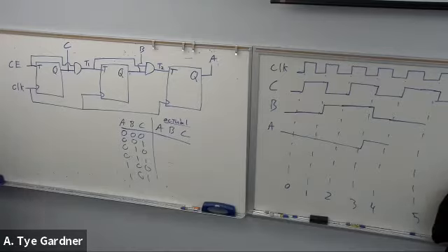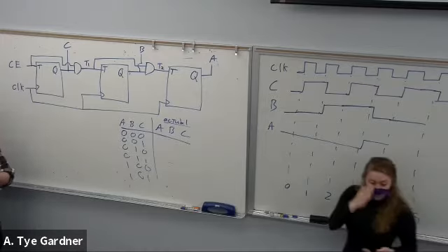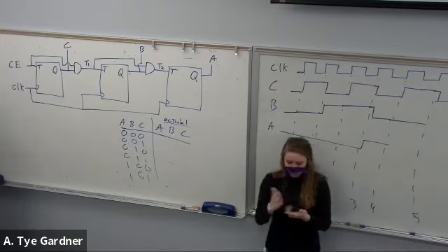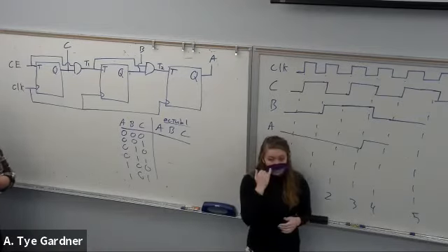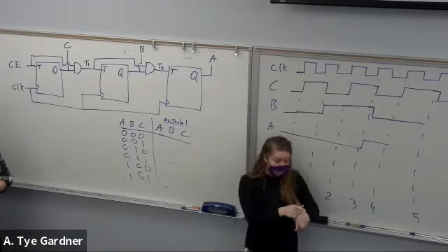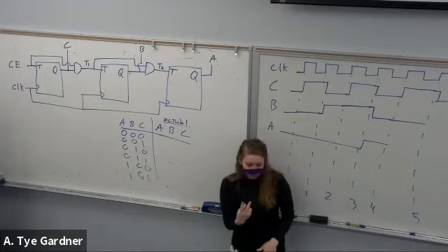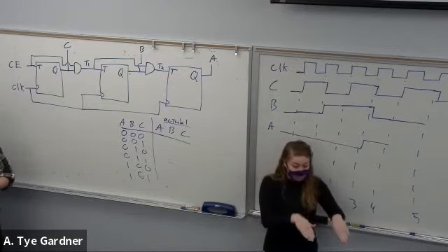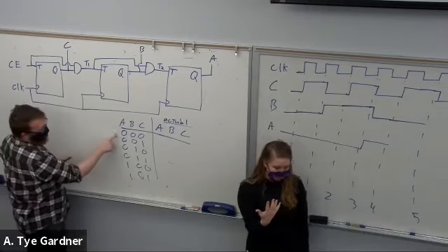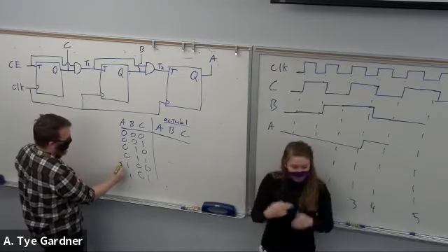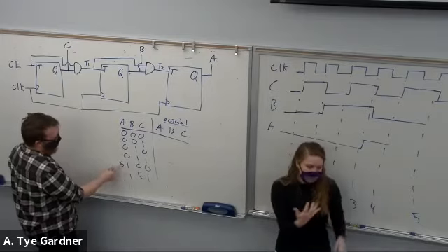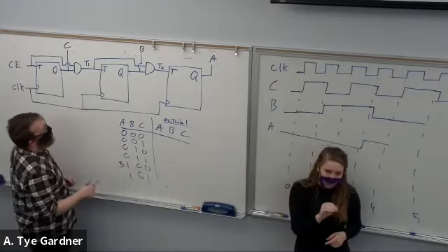Sorry, that was really not straight, was it? All right, so this is nice because now we can just count up to a number. And in fact, we can add a little bit of logic. Let's say we want to build a clock divider that is not divided by 2. I want to build a clock divider that is divided by, say, 5. Well, 1, 2, 3, 4, 5. I'm going to call this the 5th one, essentially, right? Line 5, if I'm not zero-indexed, 1, 0, 0.